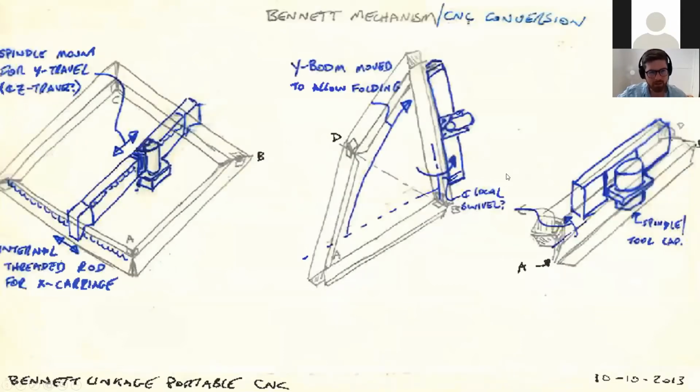One thing that kind of surprised me when I started working is that a lot of architects also bring tracing paper. So they will often iterate a drawing not by annotating the drawing itself, but by overlaying tracing paper. And then that will inform the basis of their actual professional technical drawing. So this tracing paper overlay with a different color pen, and you can see I've added some dimensions and callouts with additional annotation there. Again though, for sketching, there's no hard rules, it's whatever is a natural style. But date, name.